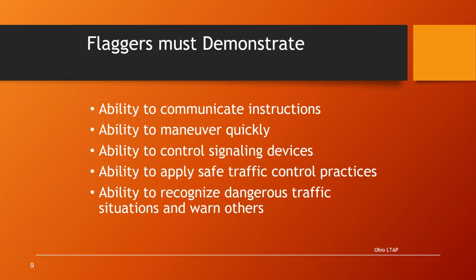And not just anyone can be a flagger. You need to pick somebody that has the ability to communicate instructions, the ability to maneuver quickly, the ability to control signaling devices and to apply safe traffic control practices, and the ability to recognize dangerous traffic situations and be able to warn others.